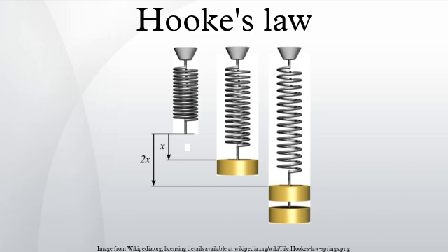Matrix representation. It is often useful to express the anisotropic form of Hooke's law in matrix notation, also called Voigt notation. To do this we take advantage of the symmetry of the stress and strain tensors and express them as six-dimensional vectors in an orthonormal coordinate system as. Then the stiffness tensor can be expressed as. And Hooke's law is written as. Similarly the compliance tensor can be written as.